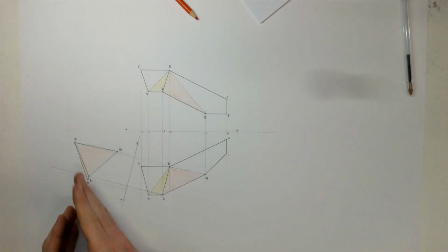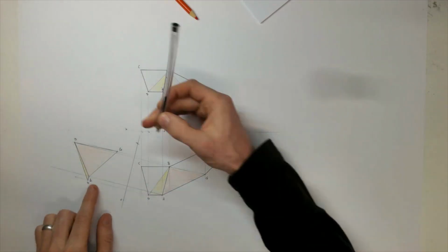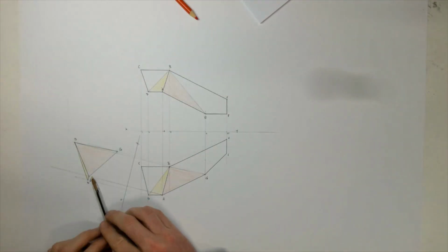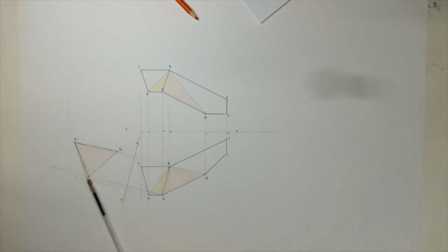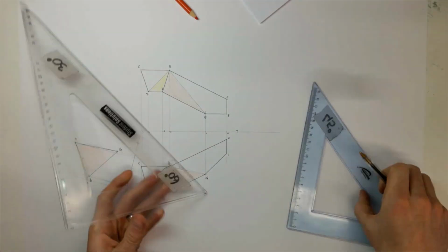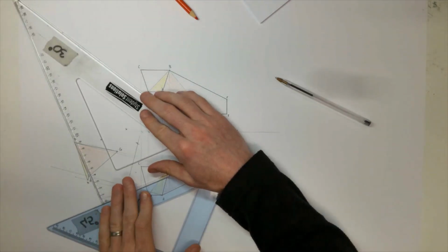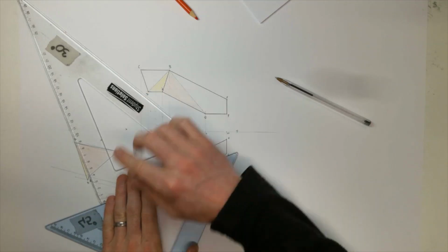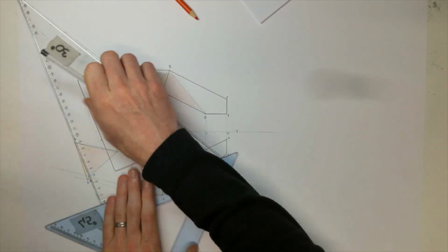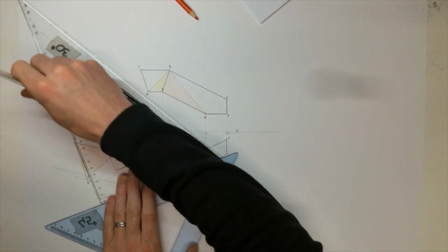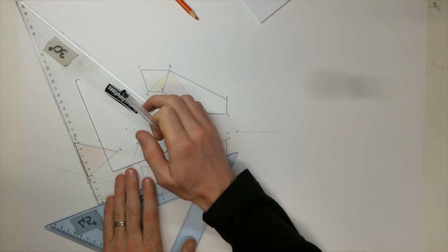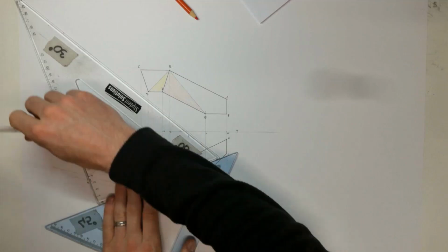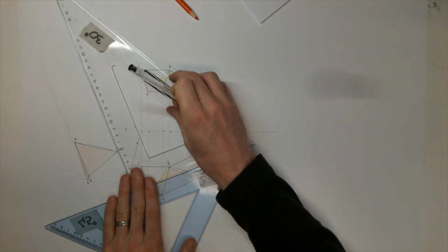Now we're going to project along that true length line. This line AB, as I said, is a true length line. So we're going to look out along it, and that will show us the dihedral angles. Projecting out along there, AB, D, and G.